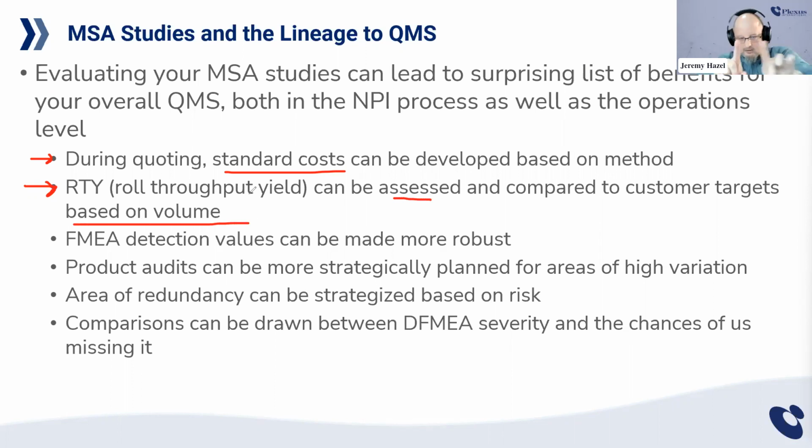This comes back to the CrossTabulation study. If I have a 12% false alarm rate, and I'm barely holding on right now to the capability in terms of the parts produced every shift that the customer wants, I should say capacity. So if you have a 12% false alarm rate and you are at the edge of capacity, what is going to happen to your delivery rate?